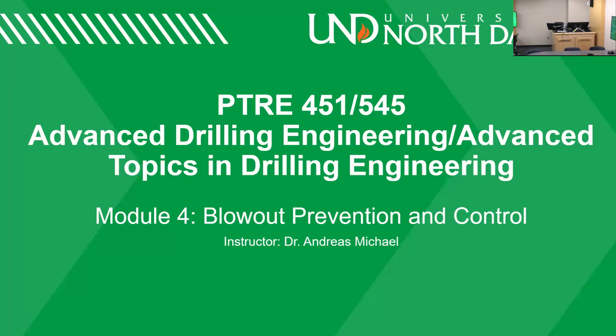Okay, this is a different example, but let's do this. I'm pumping, and then I'm rotating. I'm applying weight on the bit. I set the auto driller on, and then I think I got a kick. So I stop the auto driller, I go to 0, then I keep on lifting.